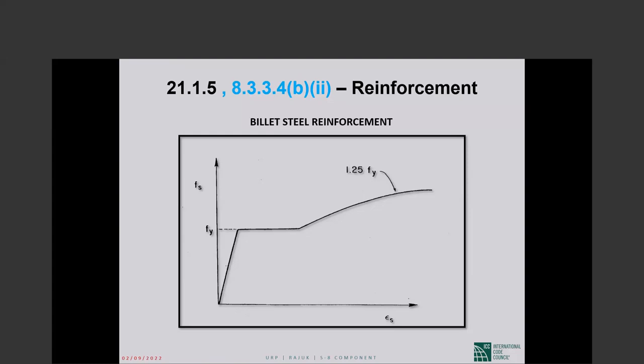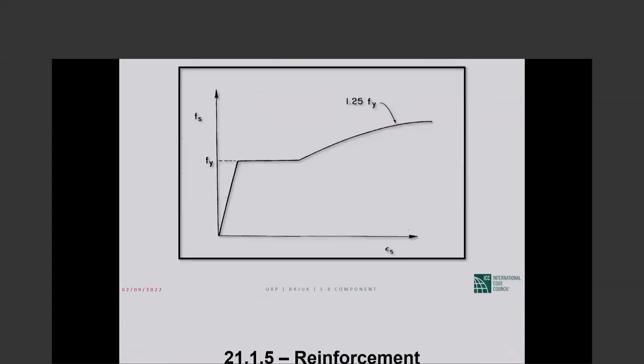Now the 125% differential between tensile and yield strength is something many steels cannot meet. So this requirement has also been a significant screen in many reinforcements. If you, Bangladesh, for instance, if you want to import reinforcement from somewhere else, China, Korea, you may find that the reinforcement doesn't meet this requirement, and then you cannot use it.